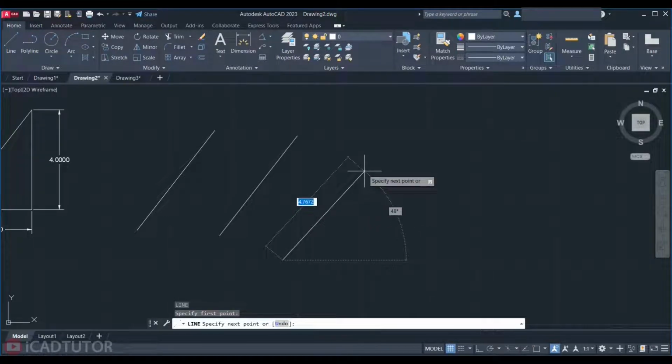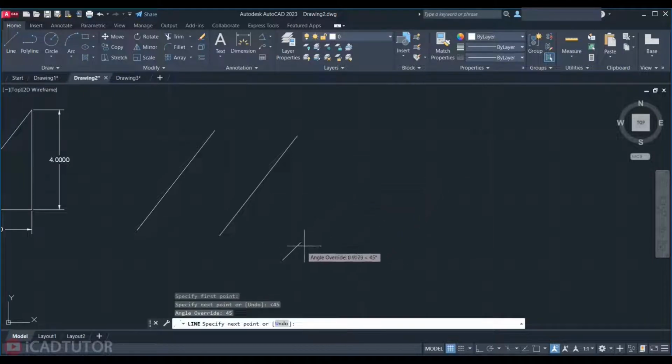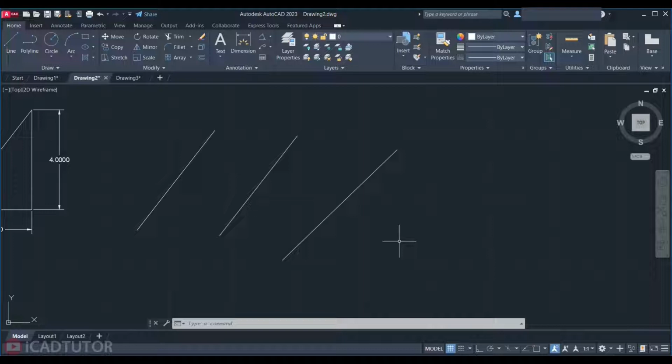To do so, I come and activate the angle by shift comma. Okay. I enter the angle size 45, enter. Look, it is locked at this angle. And you can specify the length by clicking anywhere you want in this direction. Click. Very easy. We have 2 other types of lines that I will explain in due course.